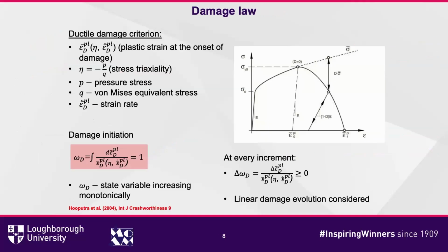For the damage law, I used a ductile damage criterion for the graphite inclusions to limit its response to the elastic region. The damage will be initiated when the plastic strain occurs in the graphite. When the damage becomes one, the element in the graphite will be removed, so the graphite can't carry any load and is regarded as damaged. Then the curve degrades to 0.